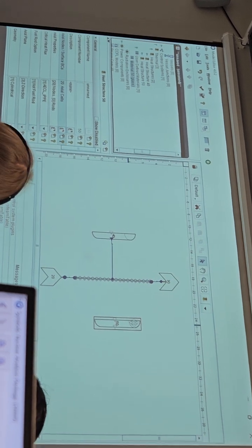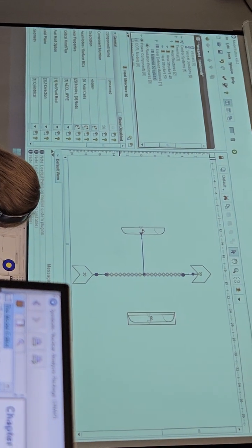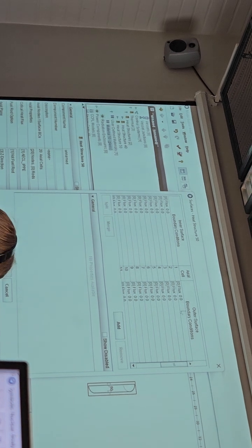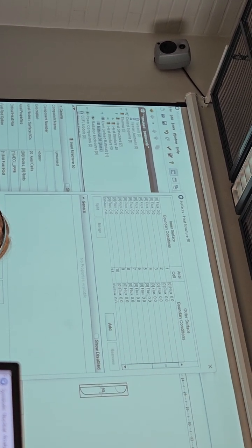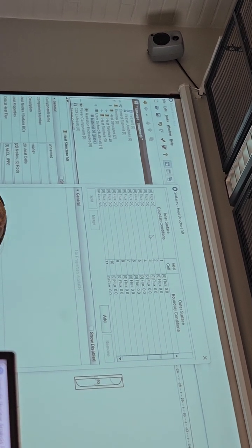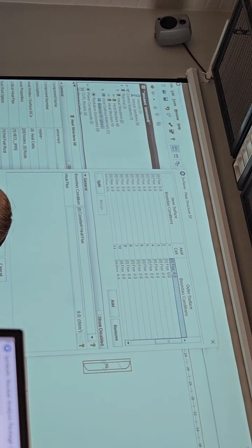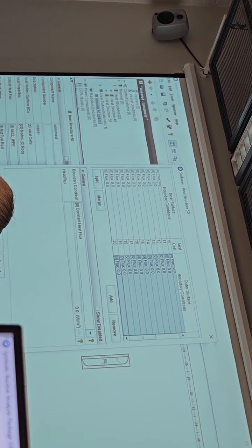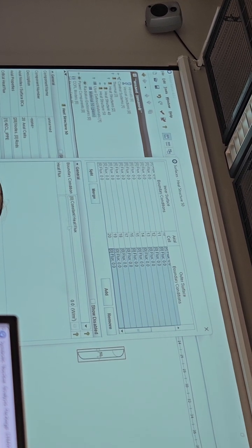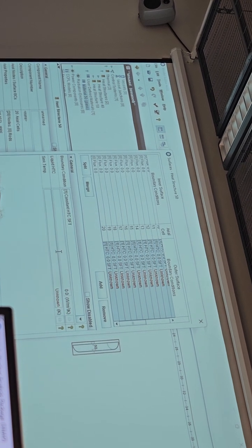If you click on the heat structure, here is the axial nodes and surface boundary conditions. If you click here, on the right side you have outer surface and on the left inner. So inner surface boundary conditions will be as the outer surface boundary conditions of the pipe when we connect it. But for the outer surface, we need to just select all the cells, all 20 cells, and then in this boundary condition section, you click here and choose a constant heat transfer coefficient.